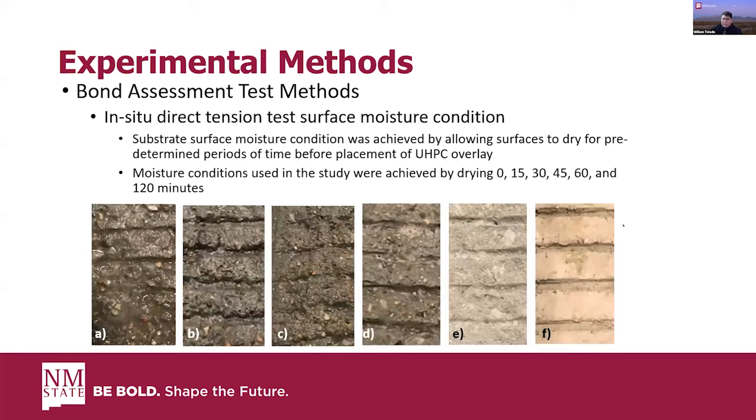Okay, then we also want to investigate substrate surface moisture conditions prior to application of the UHC overlay. So we did this by allowing surfaces to dry for predetermined times before placement of the UHC overlay. And when we say we had a drying time of 0 minutes, that just means we maintain saturation up until application of that UHC overlay. As you can see, we still have freestanding water here.